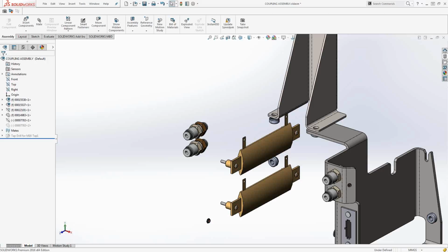All right, Raymond has a question. He's wondering, are there any improvements in the toolbox items? Yes, there are. There are actually quite a number of enhancements in the toolbox items that I didn't go over just because of time. You do have the ability now to group select the same or multiple toolbox items and to change the type of toolbox item that they are. So for instance, if you had like 10 different bolts or screws and they were all too short, you could select all of them and then specify a length that you wanted all of them to be at once.